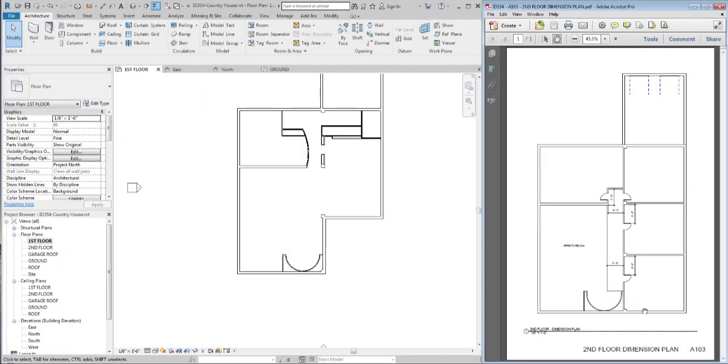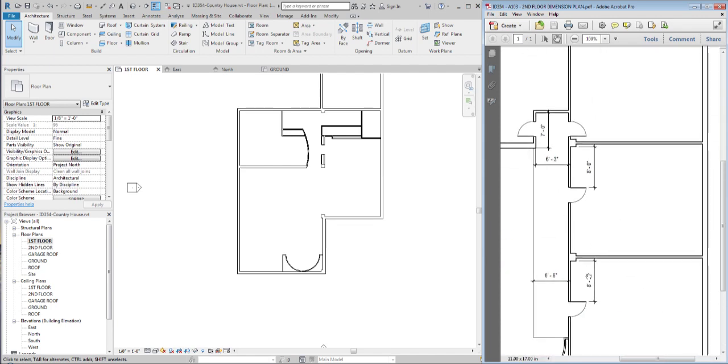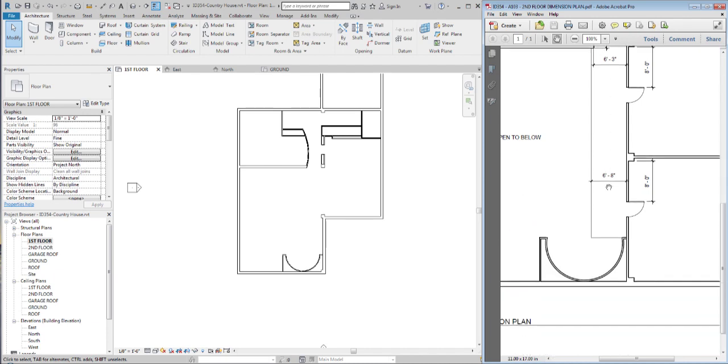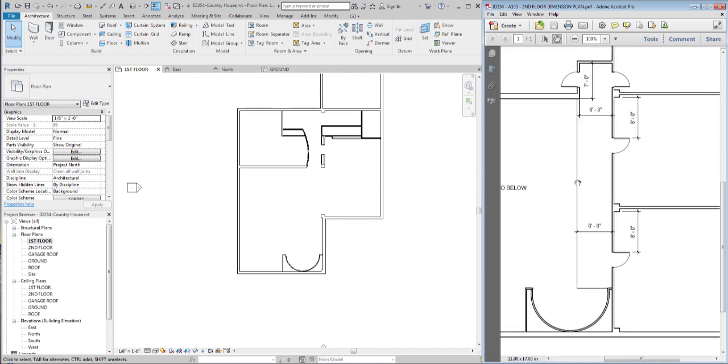Let's move on to the second floor. This I will leave to you. You should be able to build this. This long wall in here is aligned with the columns, and these walls, they are in the center line of the column. And you have a 6'3" in here for this little corridor. And this line in here represents the floor, which we are going to change after that.